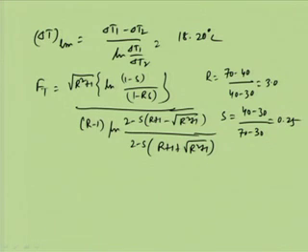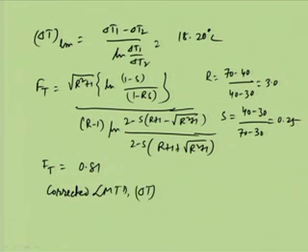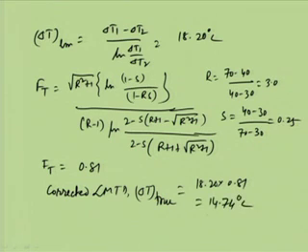Once we put these values, then Ft, the correction factor, is equal to 0.81, and this says that the corrected LMTD or delta T true equals 18.20 into 0.81, and that is equal to 14.74 degree centigrade. So, this is the corrected temperature difference. So, LMTD correction is being done.